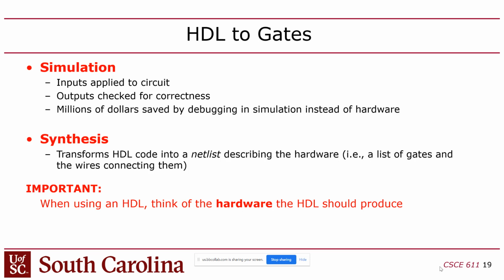Yes? When you say simulation, do you mean ModelSim? Yeah, ModelSim, exactly. We're going to use ModelSim as a simulator. So we're using two separate tools. We have ModelSim, which is the simulator. And basically the idea is that you compile your code, you open it in ModelSim, and then ModelSim is a discrete event simulator. It allows you to basically view the running of your code as if you were looking at it on a scope, on an oscilloscope, or technically a logic analyzer, right, on the bench, right? So it's like a virtual logic analyzer.